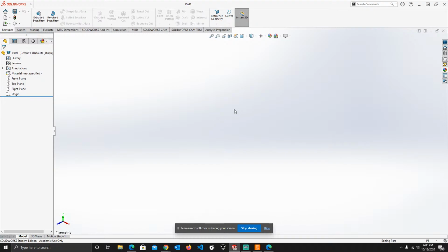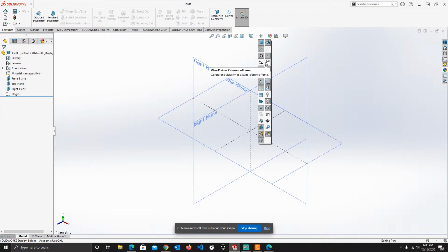So this is how you start. The first thing I like to do, and that I recommend you guys do, is set up to show those planes that I was showing before. Those are called primary planes. If you go to the eye at the top, there's a little eyeball. You click on that downward arrow, and it shows you a lot of things that you can show and hide. Primary planes I think is the best thing you can do here because once you want to draw something or make a 3D figure, then you will know where your plane is.